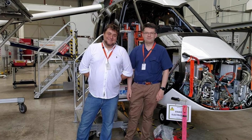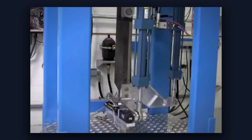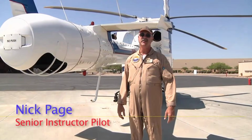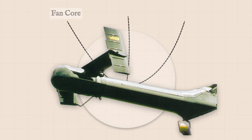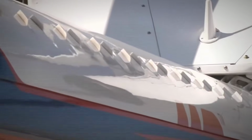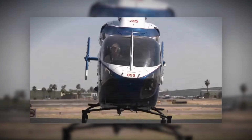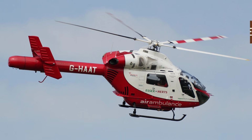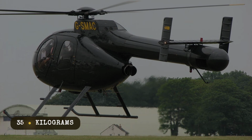Engineers have never stopped searching for better ways to tame the forces unleashed by spinning rotors. The NOTAR system, for example, replaces the tail rotor's exposed blades with a high-pressure fan buried inside the tail boom. Air is forced through slots along the boom, using the Coanda effect to create a sideways jet that counters torque. This approach trims noise by up to 6 decibels and eliminates the risk of tail rotor strikes, but it comes at a cost, an extra 35 kilograms of fan, ducting, and heat shielding.